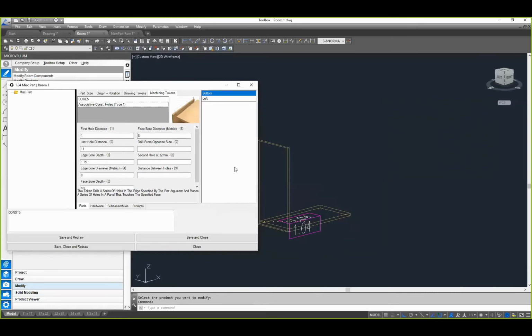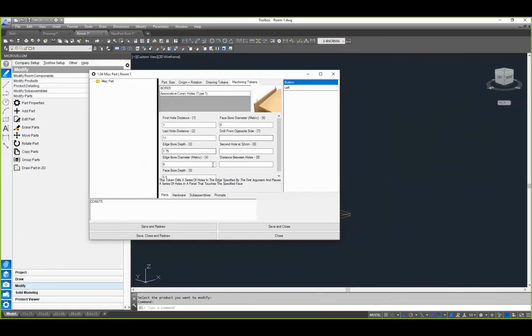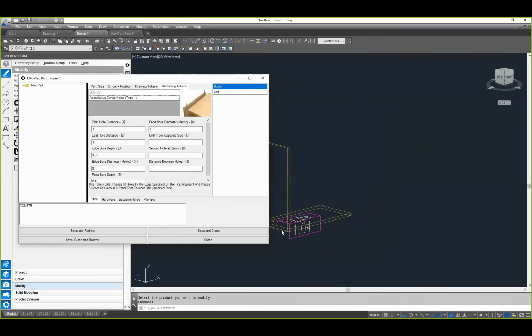And so when I do that, a little box pops up, and I think it's popped up on my other screen there, where I can specify which edge is actually going to be represented there. And so when I do that, then it'll highlight, just like it did for the show edge banding, it'll highlight which edge is going to be machined, and I can specify which one that is. And so in this case, I know that that's construction 3 because when I clicked it, it highlighted it.